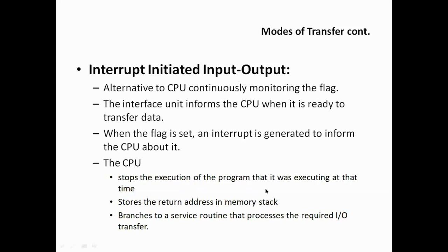I am saying that there is only an address to be stored onto a stack. Usually there is not only an address; there will be other things also related to the program that may be stored on the stack, which together with the address is called a word. But for the time being, let us suppose that only the address of the next instruction would be stored on the stack.